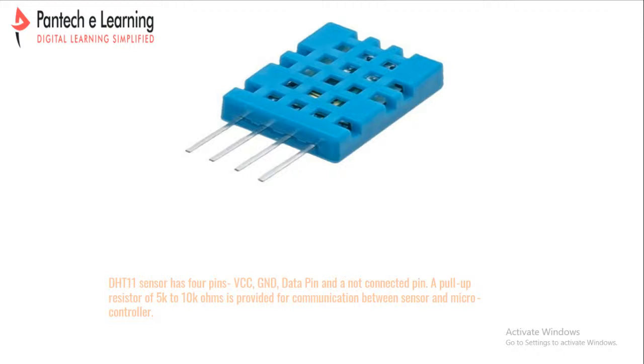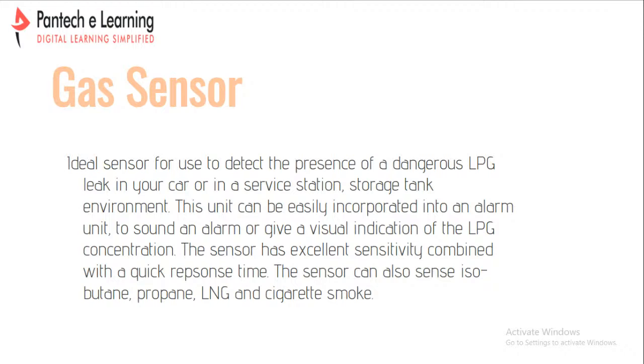One more most important thing is that the DHT11 sensor is a digital sensor. It's not analog or anything else. It is a digital sensor, and we are using a one-wire system. So in the Raspberry Pi device we have to enable one-wire. In the Raspberry Pi configuration, you have to enable the one-wire system. That is nothing more than that.